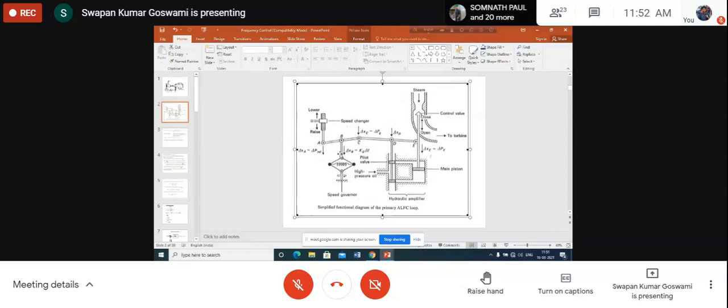Now, again, this is a rigid link. ABC is a rigid link, CDE is again a rigid link, and this is also a rigid link. Now you see that, if this position C is fixed, then what will happen? We shall discuss later how we decide the control of the position of C. As the fly balls move at a speed higher than synchronous, they will go away from each other. There will be increased outward force and increased tension on the spring.